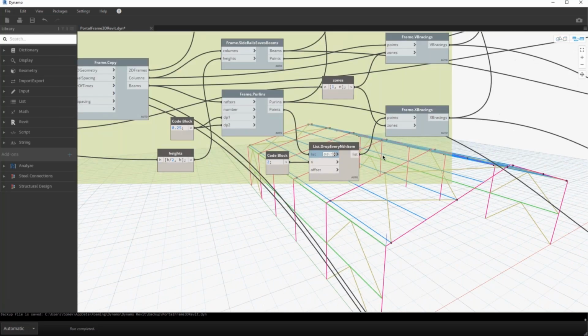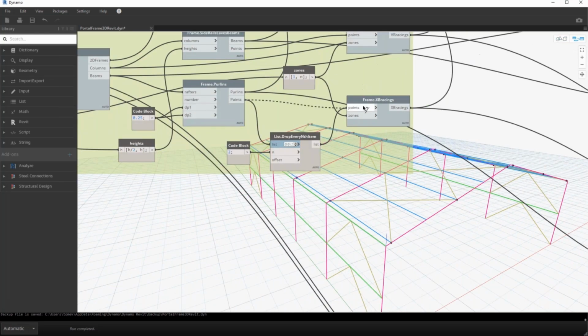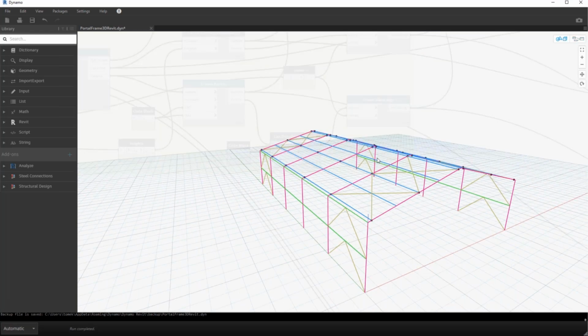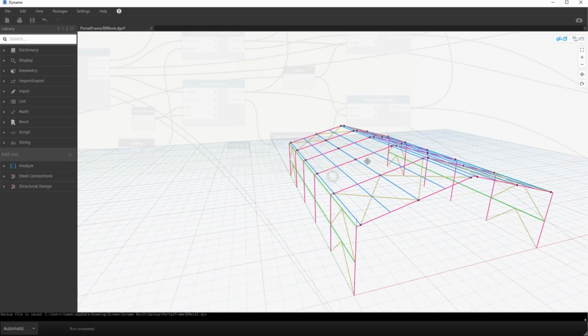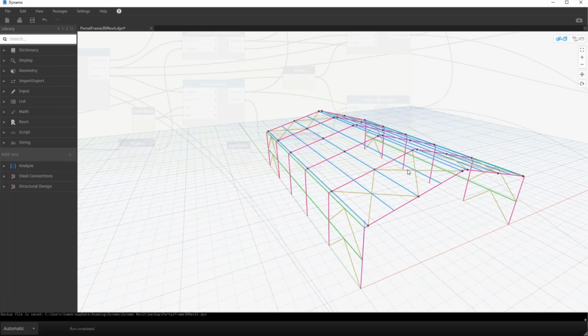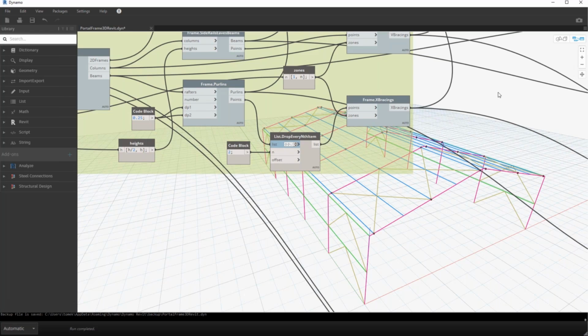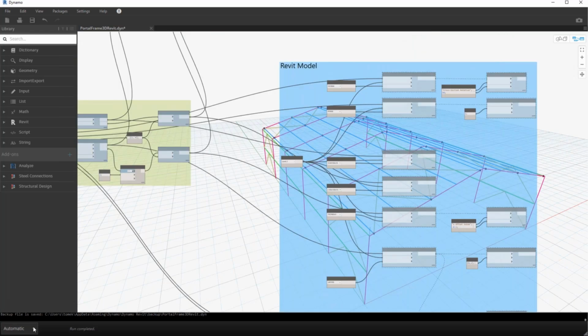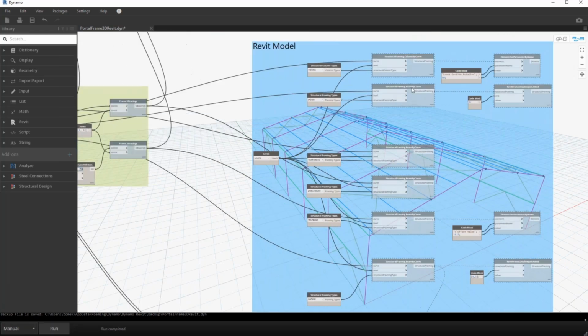We can define how the purlin and the bracing are defined, and how the spacing has been worked out. When we are doing this, I generally recommend we keep Dynamo in manual mode so that it does not create the same thing again in Revit. So this is the easiest way: keep it manual, do the Dynamo scripting, and run it manually to check how it goes.